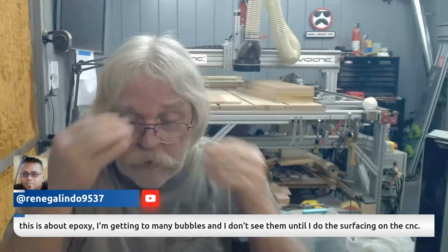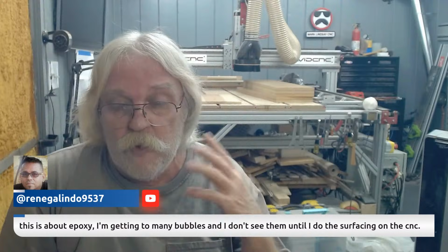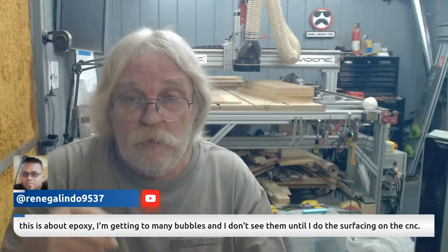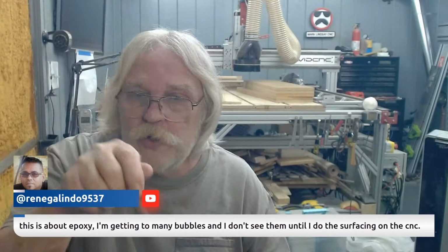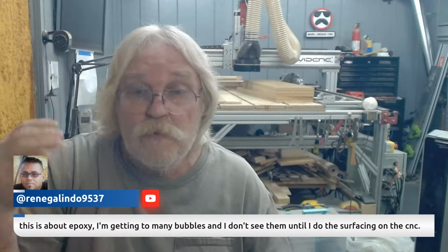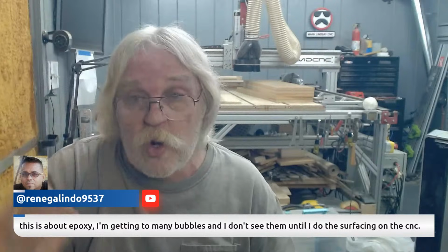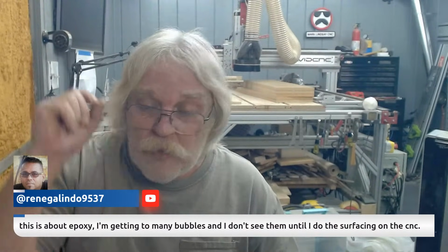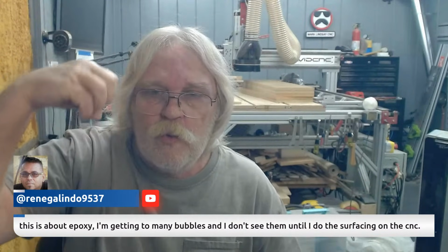What I mean by that is, on all of my epoxy projects, inlays and what have you, I will seal the wood by mixing up a little bit of clear epoxy and brushing that in. Brush it in to seal the wood before you pour the color. Like we're talking the day before you pour the color. Because every time that bit touches material, you are creating end grain.